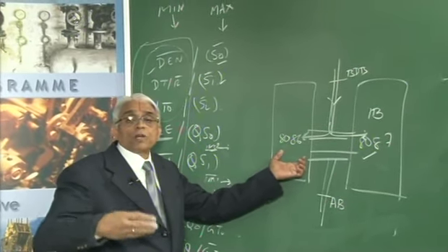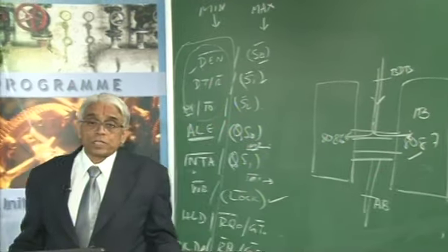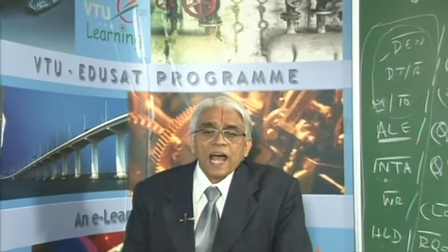If you are talking about connecting multiple 8086 processors, this signal will be used. For example, when you are performing an exchange operation, you know that we have a thing called a semaphore in operating systems, and the same thing holds good for the operation in the hardware. We have a lock prefix instruction.